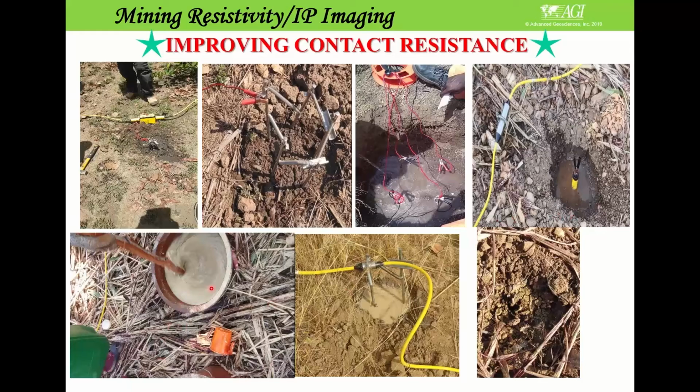If the bentonite is not very salty, a less conductive bentonite, if you can find it, you can also use it for this. There are different options of bentonite solution. Bentonite can be fine, but most of them are very salty, very conductive. But if you get one with less salt, you can also use it for non-porous electrode locations.